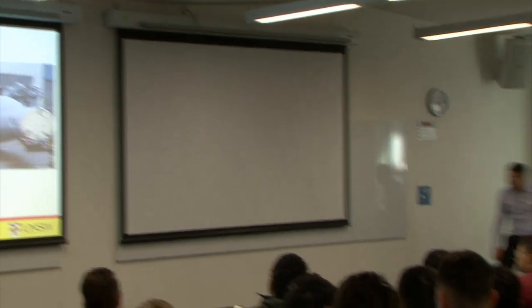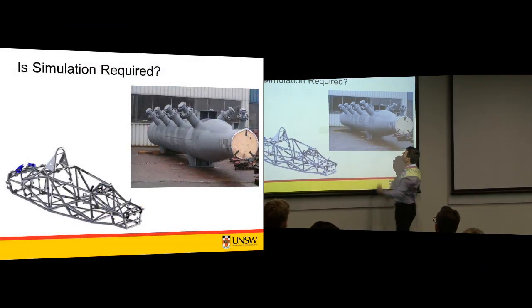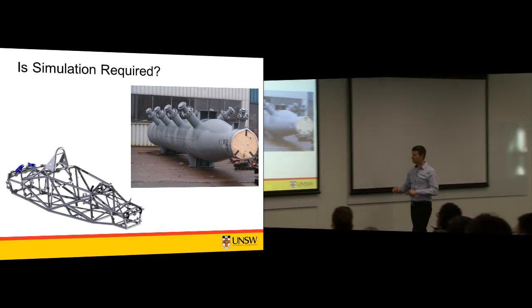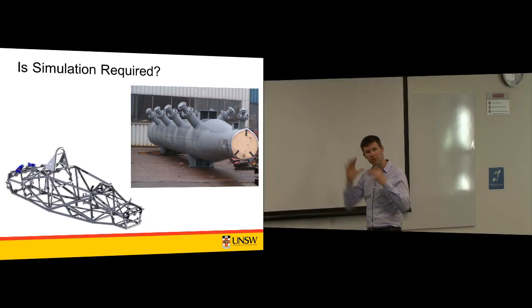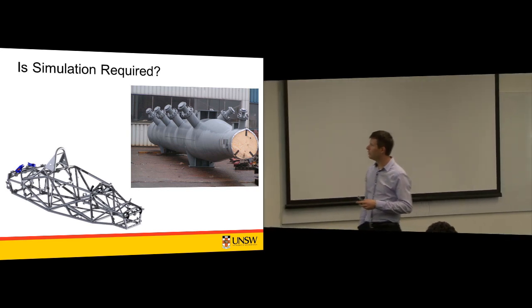They're pretty common to see. I would say this is a low pressure vessel because I can't see any compensation plates around those ports. There is some compensation around the leg. That method is a conservative method. You end up with a heavier structure than you started with.